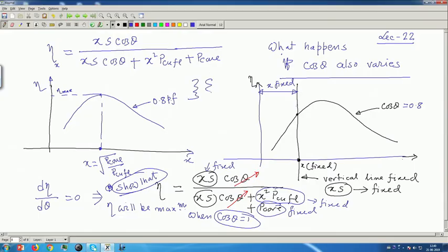This is the transformer. You always pass a given fixed current by varying the load, but in this case I will vary only cos theta to change the magnitude of the load, and then I am telling you, if it is the unity power factor, then efficiency at this fixed load, as you vary theta power factor, will be maximum here.